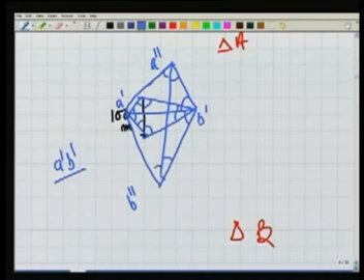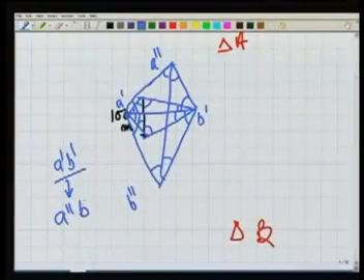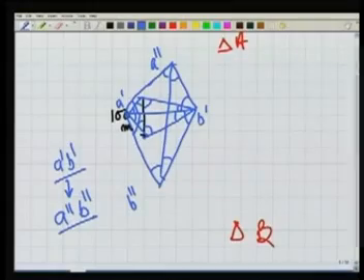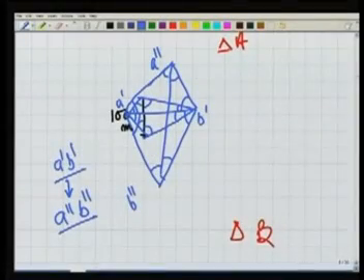Measuring these angles is not a problem because theodolite can measure any angle anywhere. So again what I am doing is starting from this A dash B dash, and all the internal angles which are measured by the theodolite, I can compute A double dash B double dash. So I know the length now of A double dash B double dash. Similarly, I will try to connect now this A double dash B double dash to AB. How can we do it?